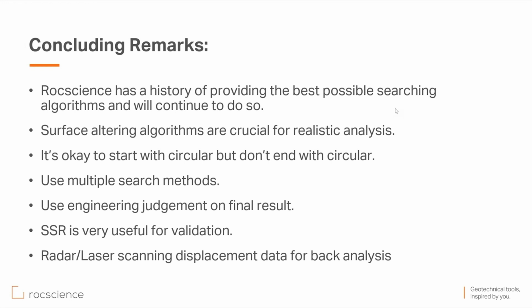So basically look at some of these parameters that you've defined, right? Look at the material strengths along the failure surface, okay? Use our safety maps. We didn't cover a lot of that in this webinar, but in 2D, we have great safety map technology, which gives you an idea of what the spatial distribution is of the factor of safety. And in 3D, we have the same facilities, but on the surface, you can see where the low factors of safety are. And these methods are actually improved with the use of multi-modal optimization.